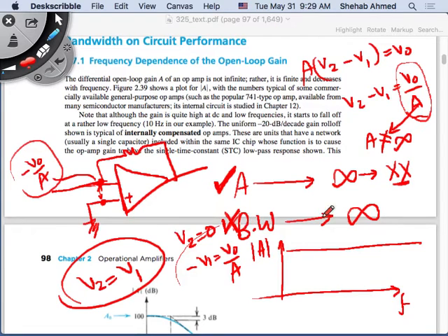We said that the bandwidth is infinite, meaning this gain A is finite, and it's equal to 1,000, for example, for any frequency. That's the other problem that we are assuming is not going to be limited by physical design. It happens to be limited by physics, right? So A will be limited by physics. We will find that it looks like a low pass filter. So it will be a high gain for low frequencies, and it will start to attenuate at high frequencies.